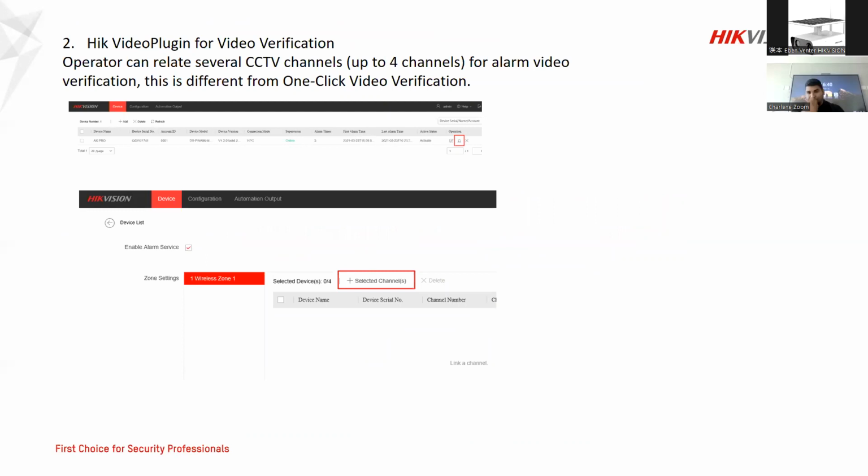Just to go a little bit back, our alarm system, our Axpro, can take up to 4 cameras without an NVR or DVR, so it gets connected directly. Bear in mind that the camera and the alarm system must be on the same network. Customers always ask, how do you retrieve footage? On our HIK-Sense and HIK cameras, we've got SD cards. Just a matter of interest, 2-line cameras can go up to 128, and our 3-line cameras can go to 256.